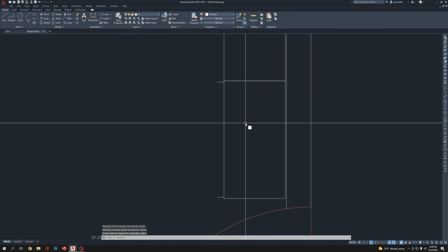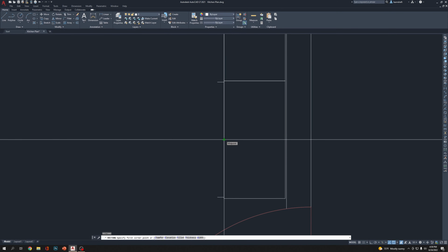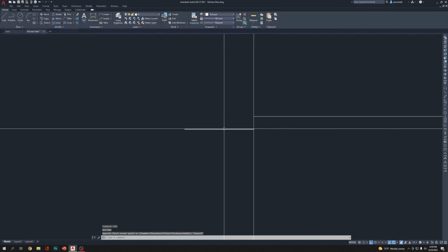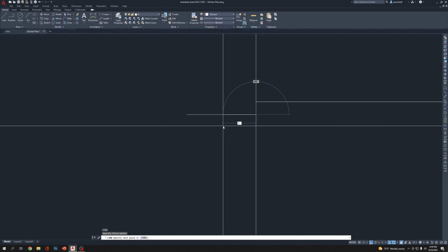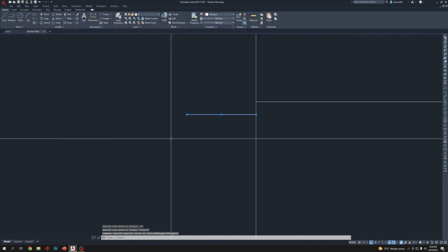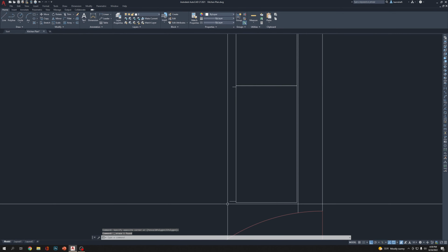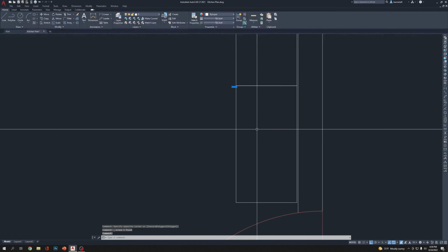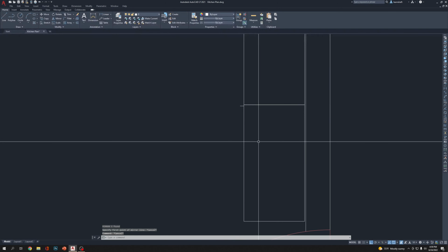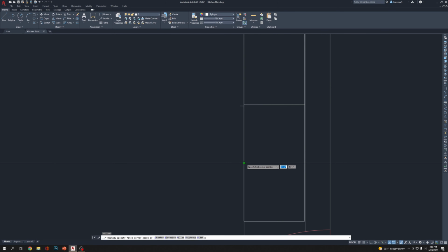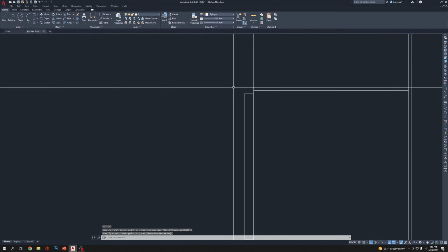and then draw REC, enter, from the center. Oh, another problem, this line should be with dimension. Click here, 0.75, enter, escape, then delete the old line, again, select it, mirror it to, no, you do not need to. So REC, enter, from the center, go there.